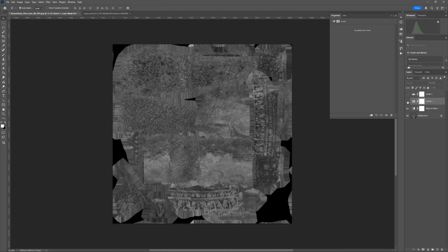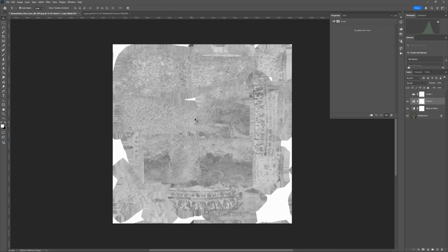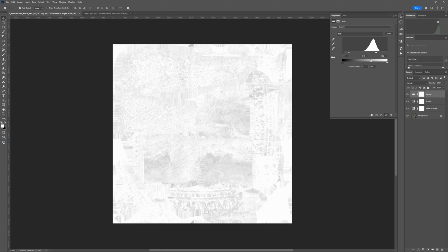Next thing that happens is you've got to invert it, because it's a roughness texture, so white means that there is no reflection at all. So we've got to tweak the levels after that, so we get it to be quite... It's going to be almost no reflection here at all, so I'm just going to kill that off a bit and do it something like that. And I find that's a good start.